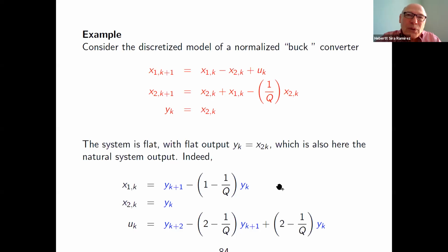All right, so this is the nature of the flat output. These parameterizations are very useful. For instance, you can find out about equilibrium directly in terms of these outputs. You can find input-output properties. You can find stability features. You can find many properties which can help you in your design. Also, in this relation, the important fact here is that the second advance of the output is related to the control input.